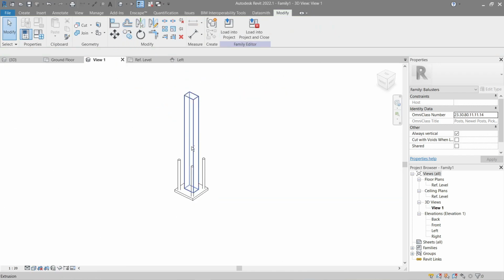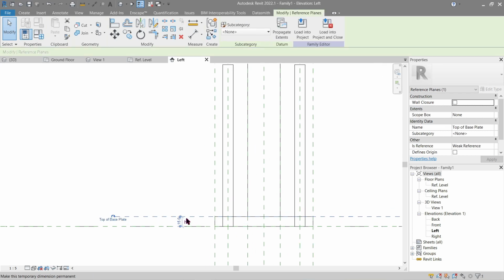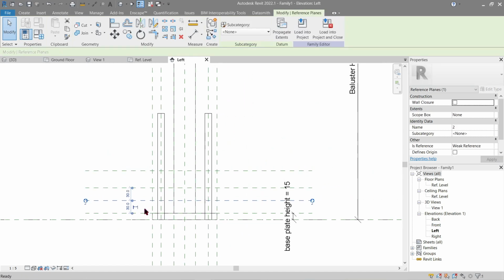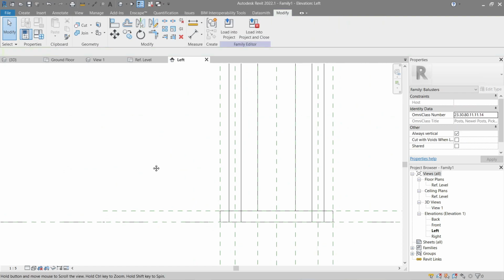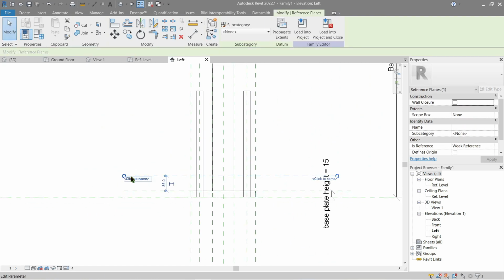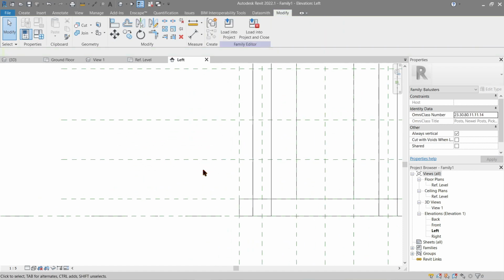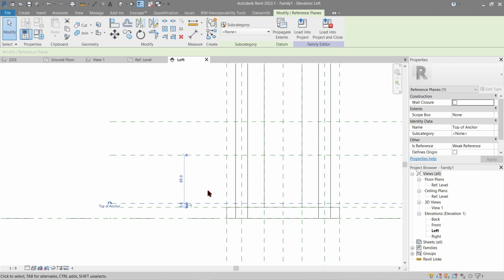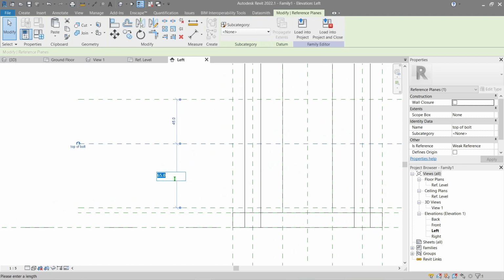Now let's look at the 3D, what's gonna look like. Alright, so you know what? Let's fix that. Going back here, let's copy this 3 times. This one will be, where's the naming? Alright, this will be top of anchor, top of bolt, this one top of washer. So the distance between them should be around maybe 5. 5 is good. Here, let's make it 8.